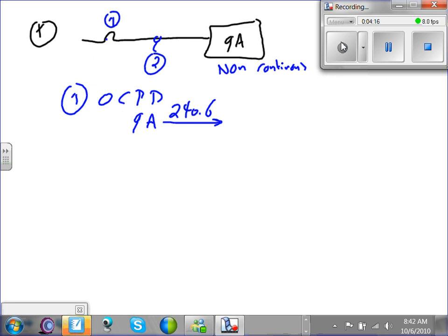Let me ask you a question. This is for Mr. Erbab. Is a 16 amp circuit breaker a standard circuit breaker? Anybody else? No? Why? It's not listed in the NEC code book. Did I tell you it's according to the NEC code book though? That's a tricky one. Well, it is not a standard because it's not listed in the NEC code book.